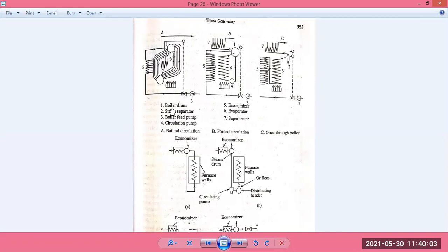Boilers with forced circulation by a special pump, called La Mont boilers, offer a certain amount of freedom in the arrangement of evaporator tubes and the boiler drum itself. Such boilers can be adapted to limitations in height and space. They are suitable for steam pressures up to 200 bar.